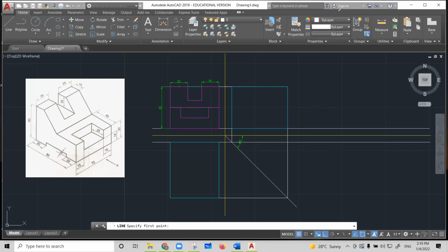Okay, so let's start drawing the lines one by one. In top view, from here, see, in manual drawing, you'll be taking the projection lines from here straight away. But with AutoCAD, you can get it, or otherwise you can take this length as 25. Then take 15 millimeter, because 15 millimeter is the width of that step. Then just close it, right? So from here, you are going to get this. Then from this end, you will also take 25, then go down for 15, and close it here.